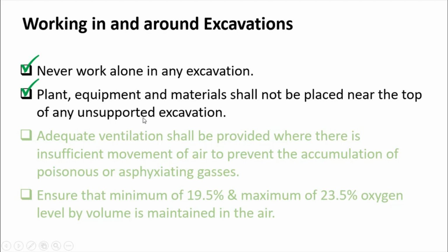Even if the excavation is supported, you are not sure if the additional load can be sustained by the support. So you need to coordinate with the designer about the capacity of that support, assess the weight of your materials, equipment and plant at that location, and give it to him to evaluate if the excavation is still safe.